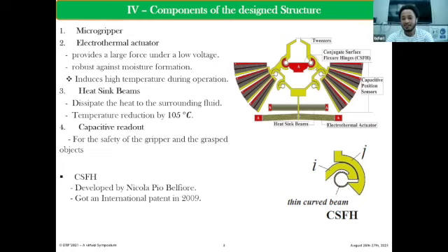Yeah, actually it is risky, but the main point is that to increase the sensitivity of the capacitive readout, we have to reduce the gaps between the fingers of the fixed combs and the movable ones. If you reduce the gap, we will get more sensitivity. That's why we reduced it to 2 micrometers to achieve the intended sensitivity. Okay, thank you very much.